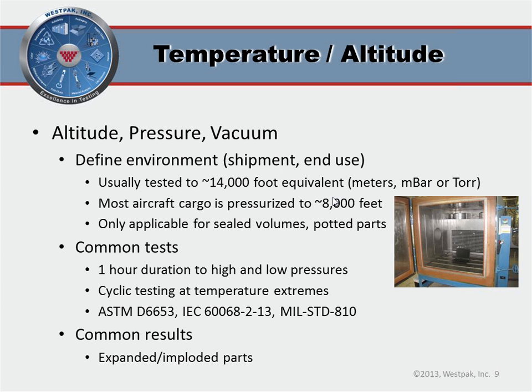The tests themselves are generally very short, 1 hour in duration at an extreme low pressure, usually 14,000 feet. For shipment, sometimes 35 or 40,000 feet, representing unpressurized aircraft. And then commonly a high pressure. So low pressure is what I just talked about. High pressure would be a negative elevation, so below sea level, maybe 1,000 feet.